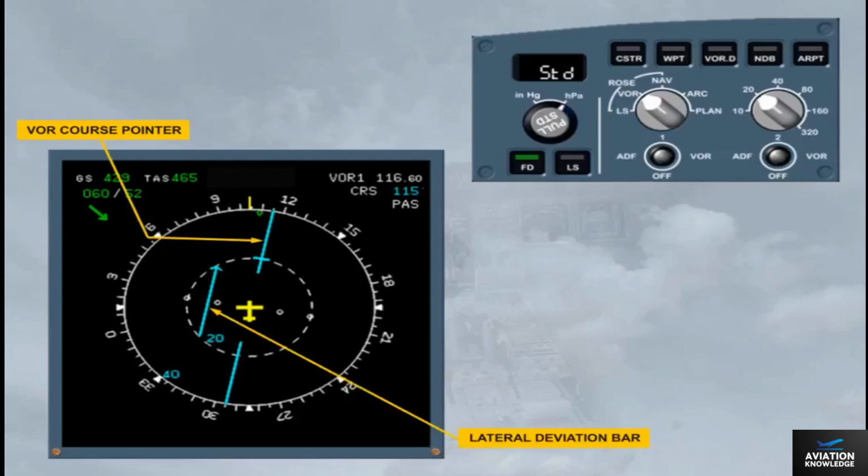In this case, VOR 1. To have this display, a course must have been selected on the MCDU RadNav page. Like ROSE ILS, the information about the tuned frequency, the selected course and which navaid, here PAS, is displayed in the top right-hand corner. Also the MCDU selected approach type, VOR or GPS, is displayed as shown.